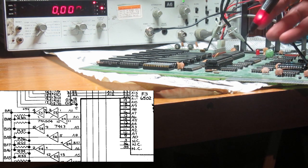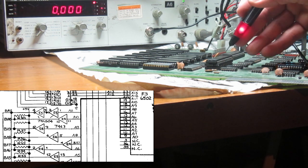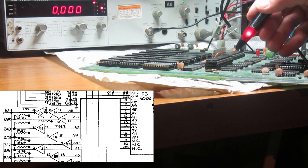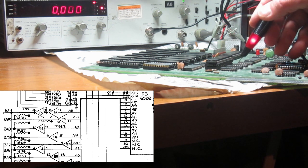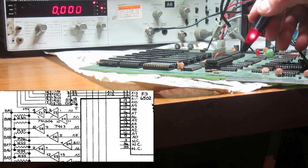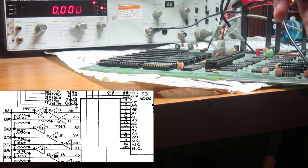We can check other buffers, but it's the same thing. You check the input after you have checked all the addresses are generated correctly. You check the input of the buffer for the signal reaching the input, and then the output of the buffer. If we check with the oscilloscope, we will find the same exact signal on the input of the buffer and on the output.